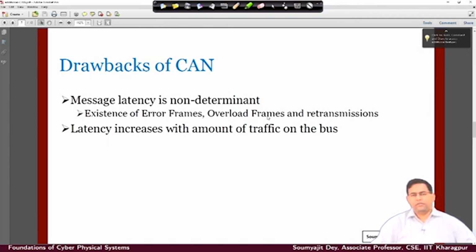So one question that may come is, how can multiple ECUs be connected on the CAN bus, and how can the periodicities then be defined? Well, we have understood one thing: there is this arbitration, that means if you have a low priority message, you should not try to send it at the times when the high priority messages are being sent, right? Now, it depends on how these messages are generated. If these messages are getting generated by some periodic sensor, let's say, or some periodic controller, if it's a control message, right, then well, you will like to send them with the same periodicity.